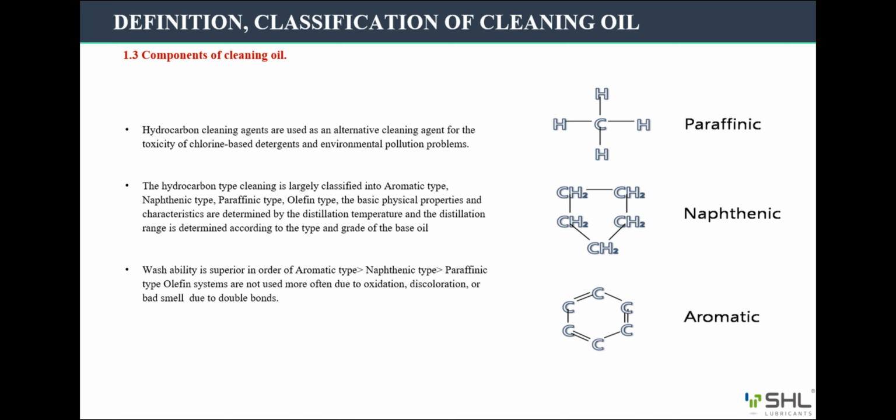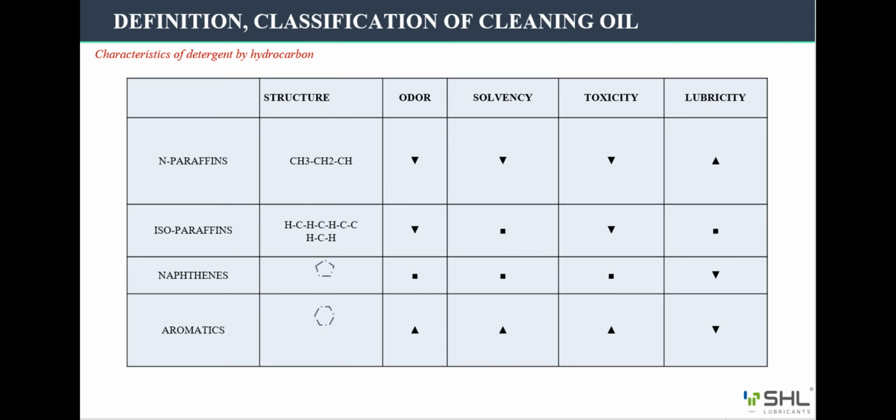For washability, it is superior in order of aromatic type, naphthenic type, paraffinic type. Olefin systems are not used often due to oxidation, discoloration, or bad smell due to double bonds. Next is the characteristics of detergent by hydrocarbon. Here is a table listing hydrocarbons and their properties.